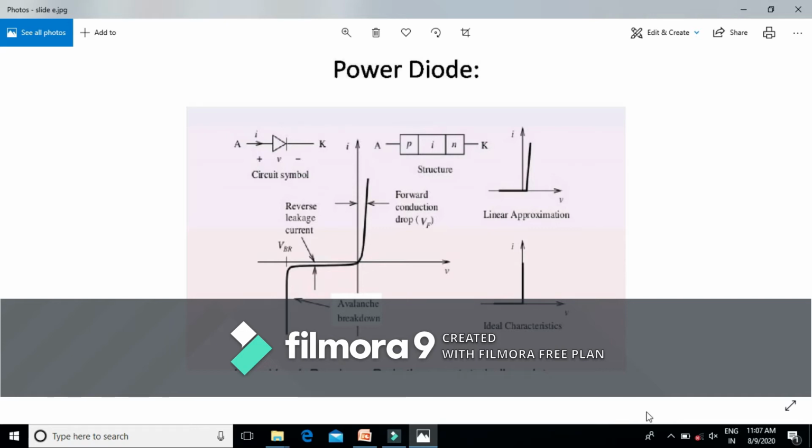While during reverse biasing, if P is connected to the negative terminal of the battery and N is connected to the positive of the battery, the width of the depletion layer gets increased. Also, we should keep in mind that a rise in junction temperature decreases the width of the depletion layer. As the barrier potential depends on the width of the depletion layer, the barrier potential decreases with a rise in junction temperature.